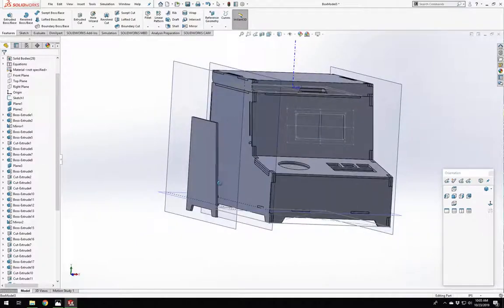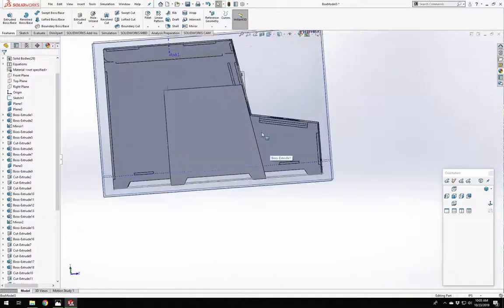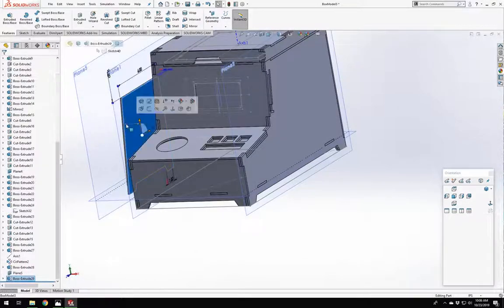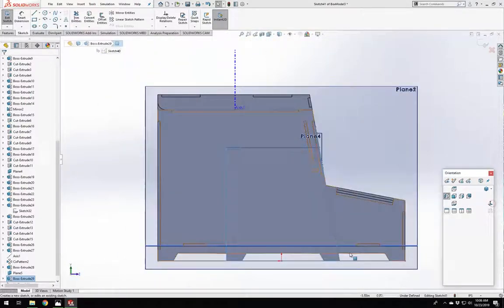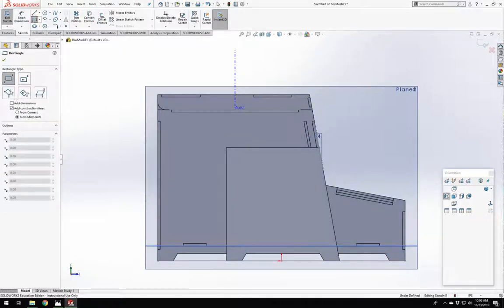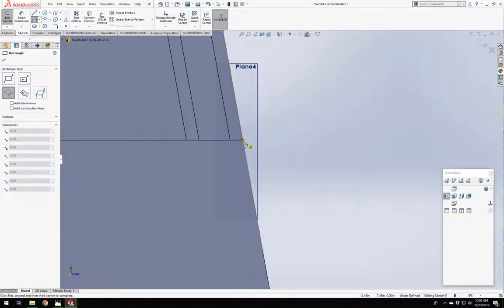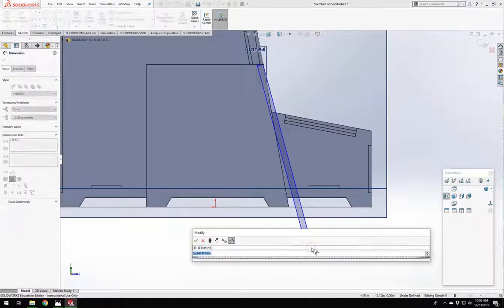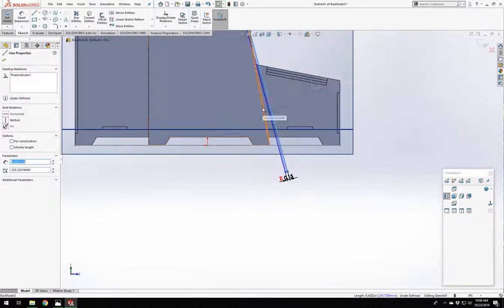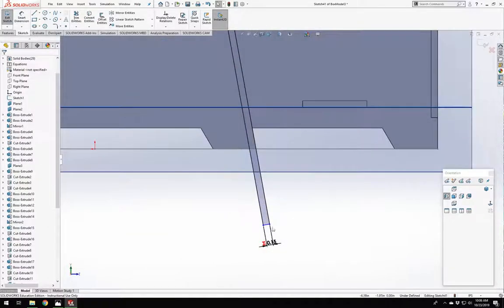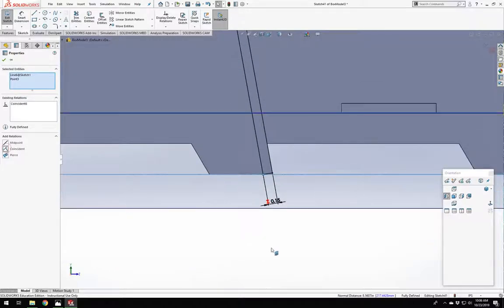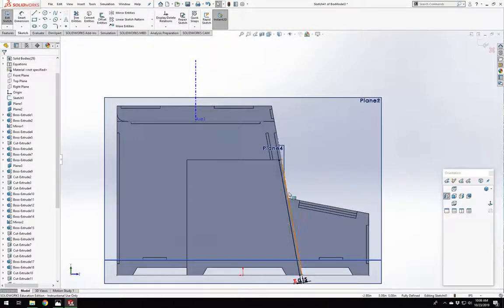So the way we're going to do the front in this case is going to be very similar. We could do it similar to that, but I actually think I'm going to do it slightly differently in this case. So what I'm actually going to do is start from this surface. I'm going to take my front panel, which I'm going to do as a rectangle. I know it's going to be the same height as the top here. We know it's going to have a mat thickness, same as our global variable. It's going to be collinear with that front edge. And it's going to come almost to the surface, so we want to get that back point on the surface. There we go, and our front point matches up like that. Great, so that's going to be our front panel.